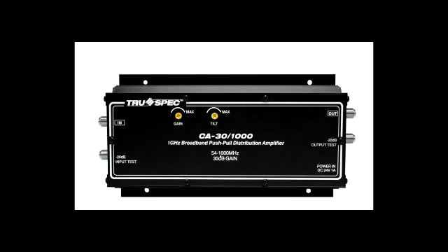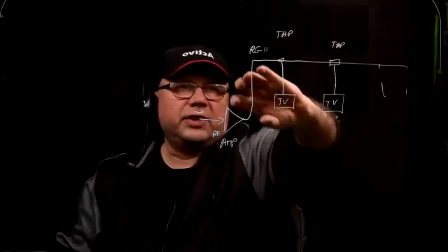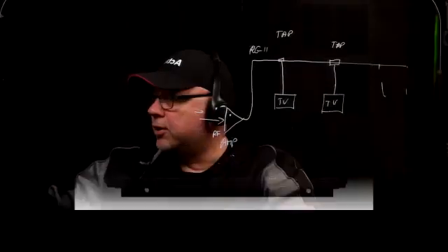So here are the controls of an RF amp. Here's the input that the signal travels through from the city. Let's say it has, I don't know, maybe 6 dB of strength. Then after that, you raise the amplifier's volume, or the gain. You can control that. So the signal has a certain strength at the output of this amplifier, injected over the whole system. It has to have enough strength to carry to the furthest TV.